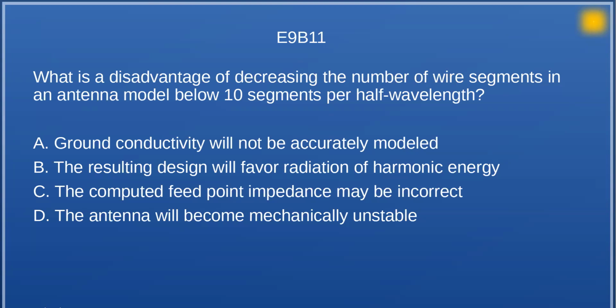Or, I mean, you can create your own antenna. That's kind of what it's used for, to model different antennas, not necessarily a real one. They'll have a bunch of samples that you can call up and modify. You can just do it from scratch. And you define it like, say you want to do a dipole. You would define element 1 or wire 1, excuse me, and you give it an XYZ starting point and an XYZ ending point.